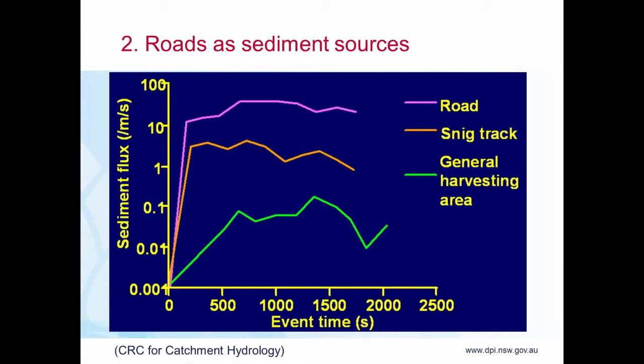So you can see here that they are at least an order of magnitude more important in terms of the contribution to sediment concentrations that they make relative to, say, snig tracks or what you might call skid trails and the general sort of harvest area. So that's why we focus a lot of our effort on making sure that they're managed properly to reduce the likelihood of impacts on waterways.